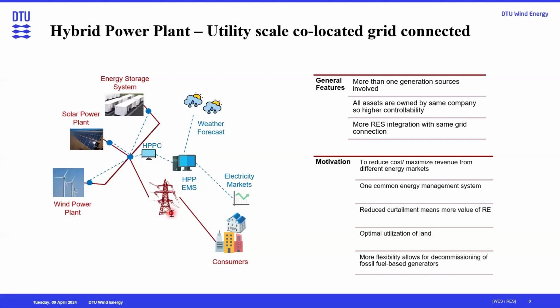So I'm going back to this figure. What you can see, if you assume that the grid connection here is, let's say, 100 megawatt, it allows you to connect much more than 100 megawatt, typically two times or even more of renewable plants beyond this connection. So with the given grid connection, you are able to connect much more renewable into the system.